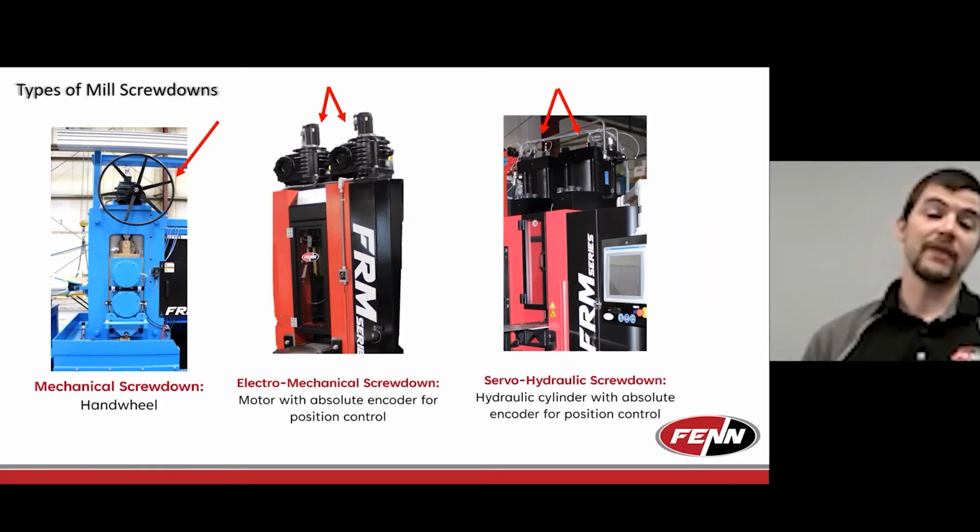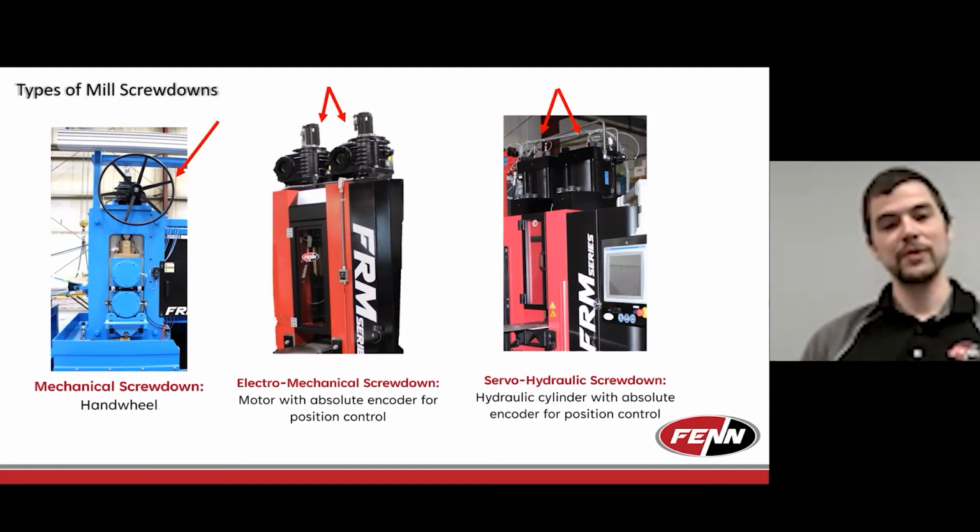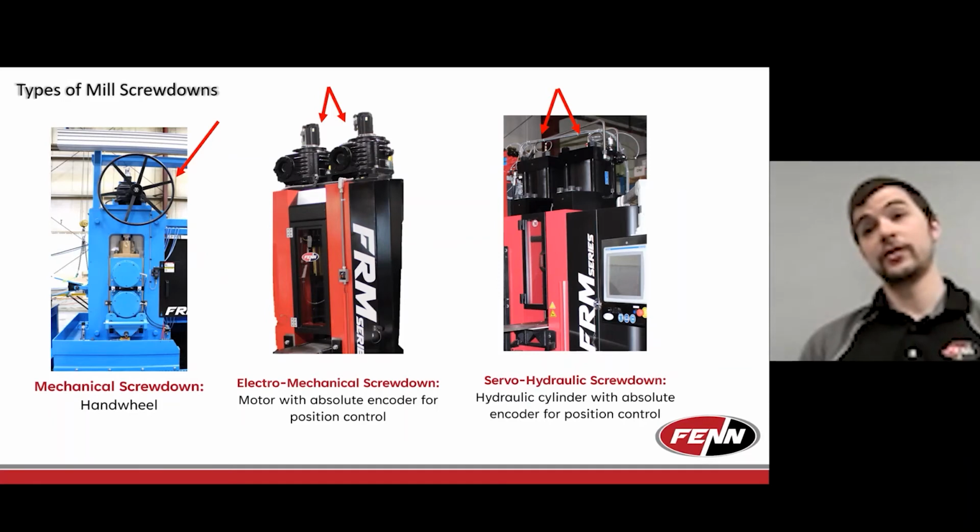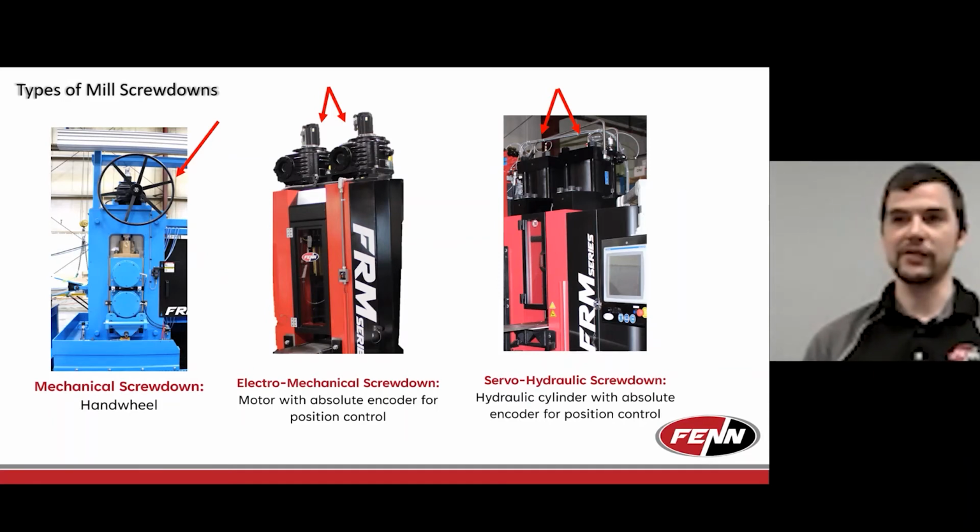It's really hard to have electromechanical that can drive under load as well as move quickly, because that really affects the motor size and the reductions in terms of precision of motion. Servo hydraulics, they can do all 3. You can move fast, you can move under load, and they can hold a position very tight and accurately, so they can make minute adjustments.